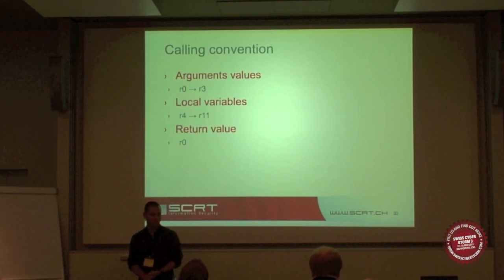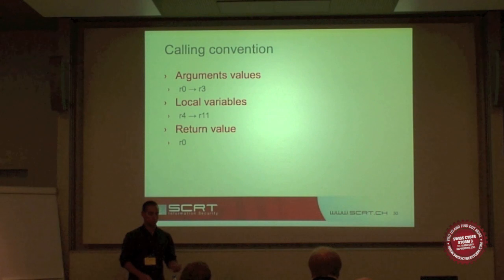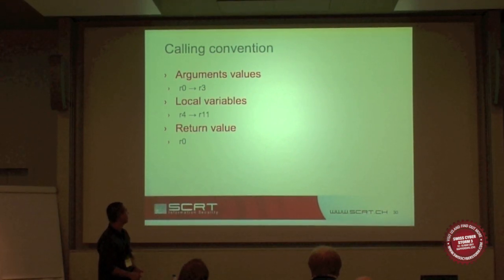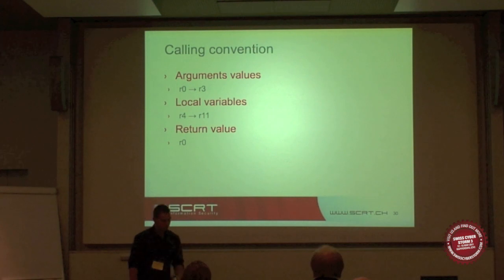So another useful thing is the calling convention. The arguments are stored in the registers R0 up to R3. The local variables are stored in R4 to R11, and the return value is stored in R0.